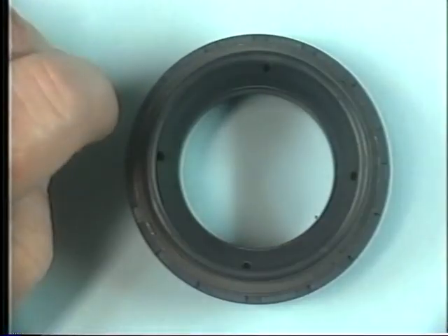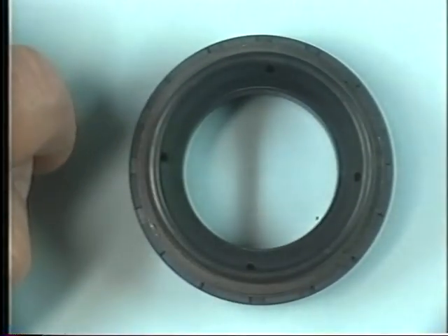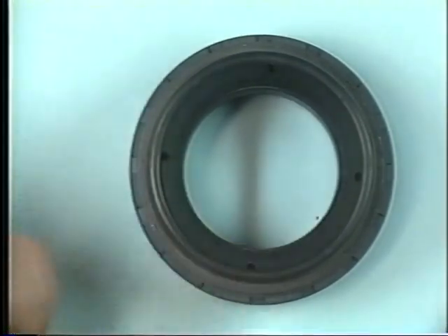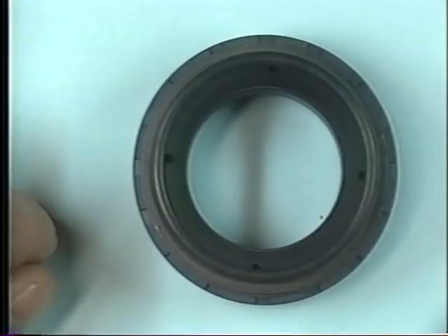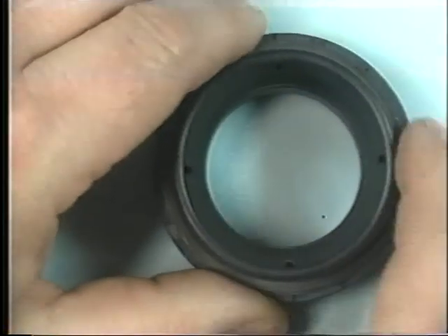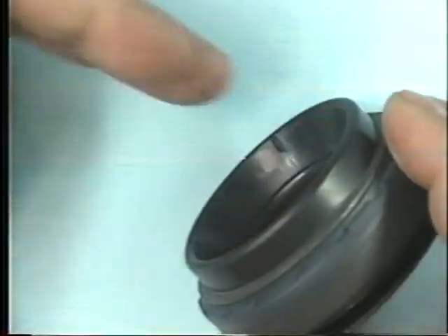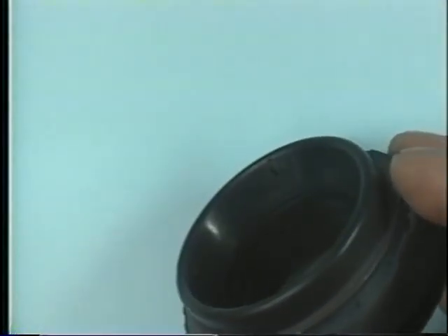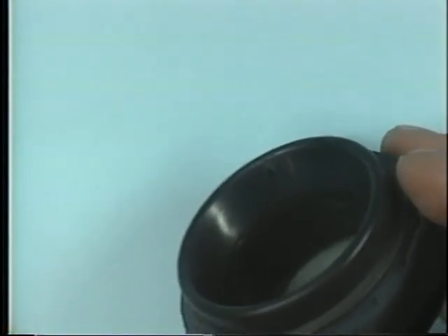Now, the other seal is rather unique. This is the oil seal. Kind of interesting, it's got a beveled edge here. This is the leading edge, where the axle shaft will be coming in. Now, when you're trying to reinstall the axle shaft, obviously this is a long way in, so it's important to keep rotating the axle shaft. As you're coming in, if you rotate the shaft, it's going to walk right up that beveled edge and slide into place for you without causing any damage. Otherwise, trying to push it through there just doesn't work well.